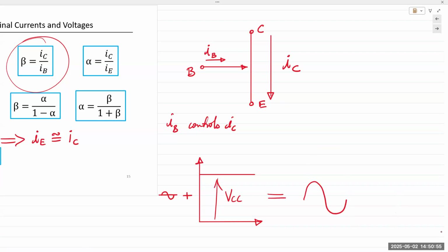But if you now disturb the base and you apply an AC signal, your base current or your base voltage is either going up or it's added on to your base voltage, or it's subtracting from the base voltage. So depending on the AC signal you're applying, your base input current is also changing. The change will be very, very tiny. But the effect on the collector side would be really big.